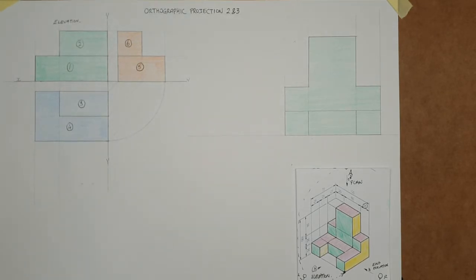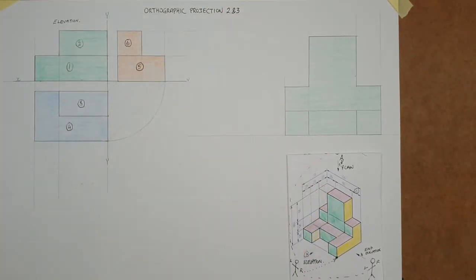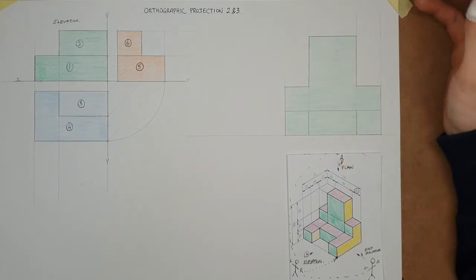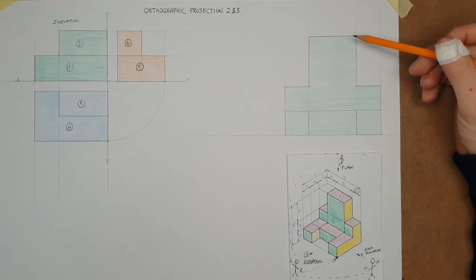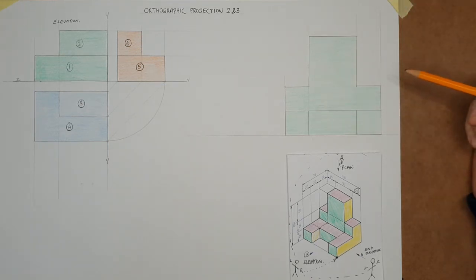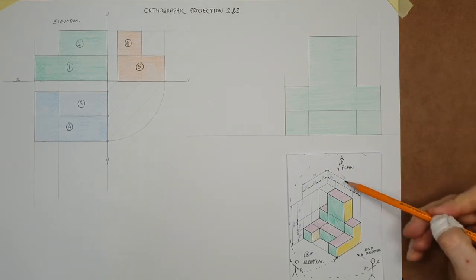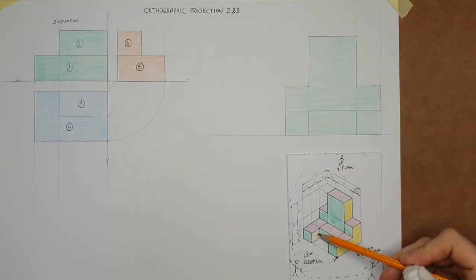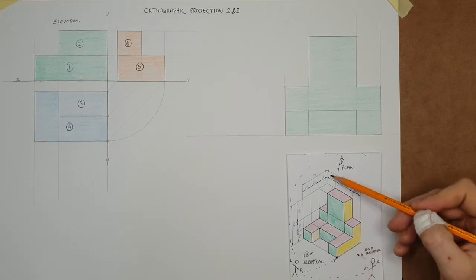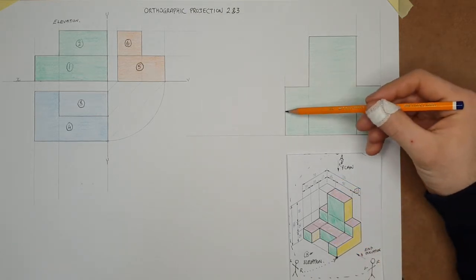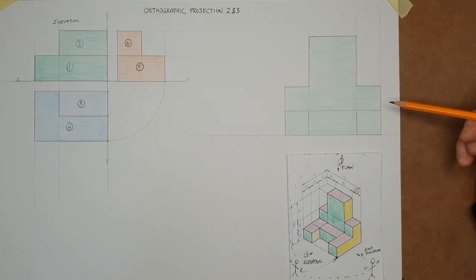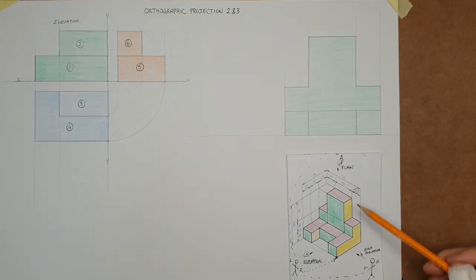We're going to move on now, and we're going to go down and view from top of the object, looking down in the top, seeing what we can see from up in the air, and draw our plan. As mentioned in previous examples, the plan is going to be directly under the elevation. The plan features two dimensions, lengths and depths. So the length, depth and height. So we have the lengths of the 25, the 50 and the 25. We've already marked in those, so 25, 50 and 25. The depths are 25, 25 and 25. They're the measurements we're going to need to produce what we can see in this purple orientation here.